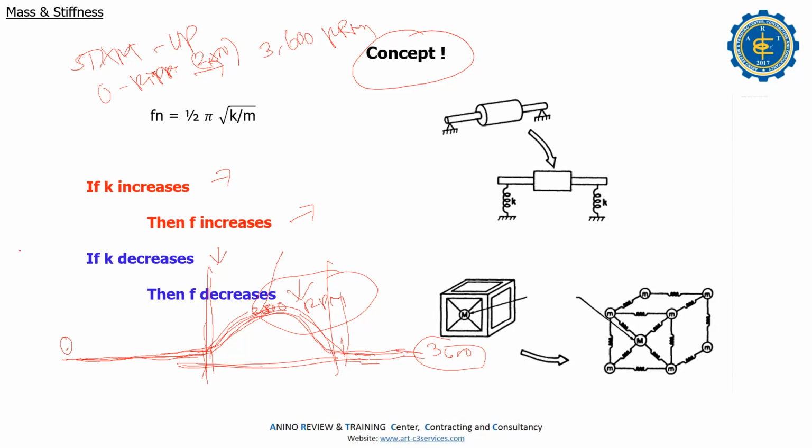We will focus on the turbine, right? Don't eliminate the previous one, because that is another scenario. If you have a turbine and you have a generator, they have a normal critical speed. So to prevent this and make it safe, you must ramp up or directly pass the critical speed.